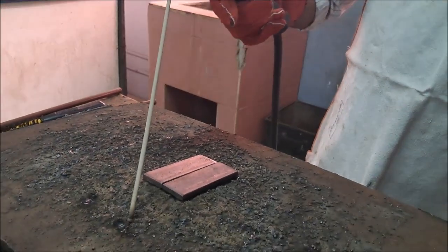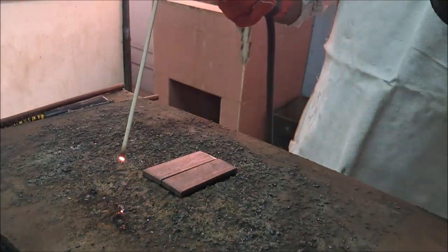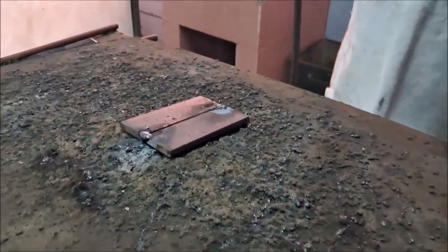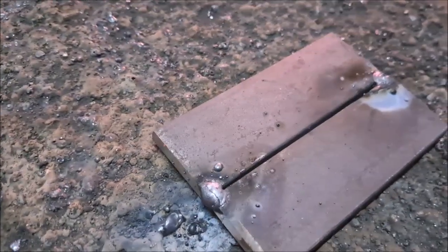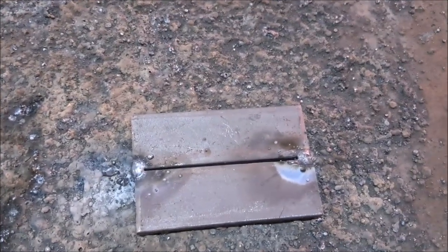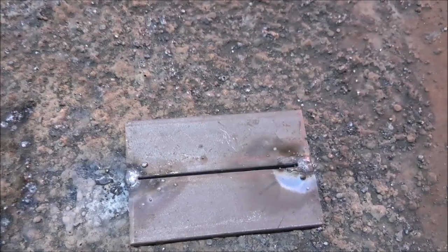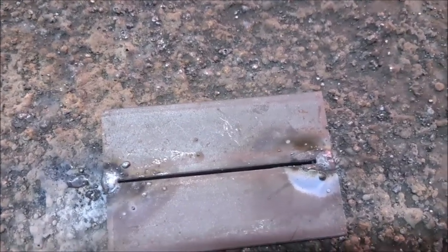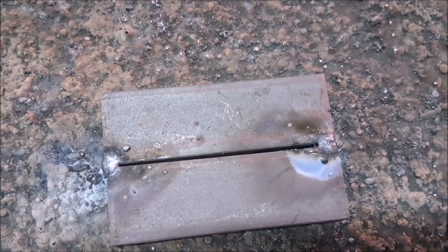After scratching, you have to do tag welding. First do the tag at the edge of the top one and the edge of the bottom one, to maintain this plane surface like this way. The top one, the bottom one, to make the dot. This is the tag welding. If you don't do tag welding and go directly to welding, the workpiece will be bent. So before you start the welding process, maintain the tag on the top and bottom, otherwise your workpiece will be bent.